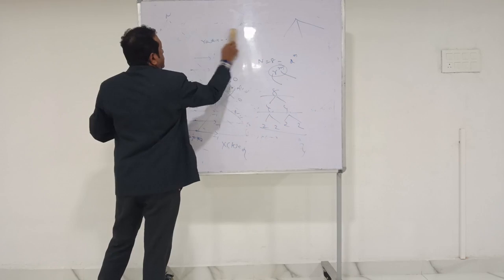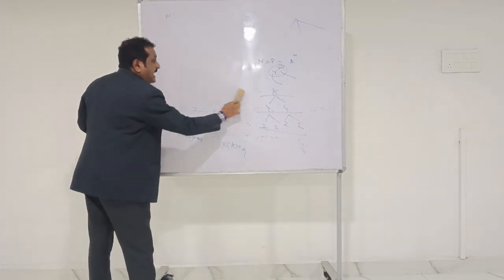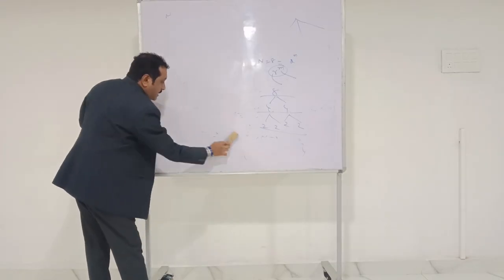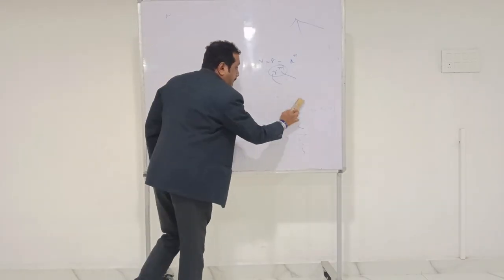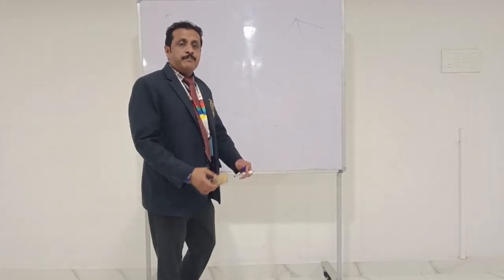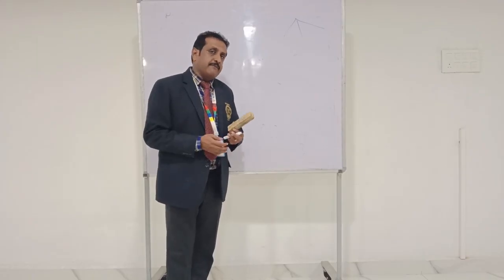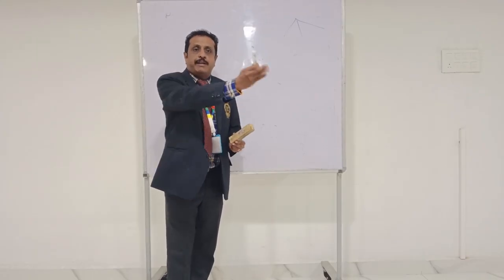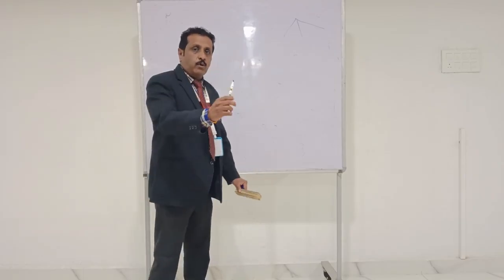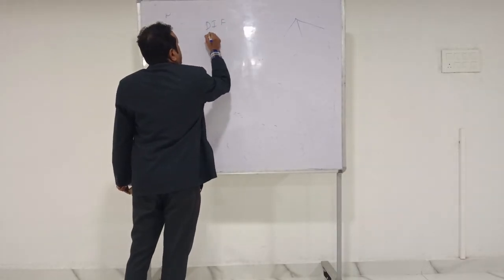Now we are going to discuss the basics of the next algorithm, DIF, because DIT is over. Whatever the algorithm may be, your procedure may be different, but the final answer will be the same. Both approaches are used to compute the DFT with a reduced number of calculations, from time domain to frequency domain, if your signal is a discrete signal. Now we go with DIF, decimation in frequency.